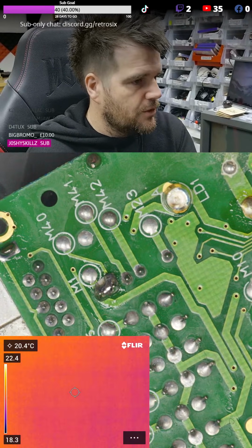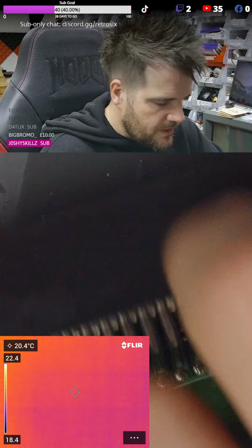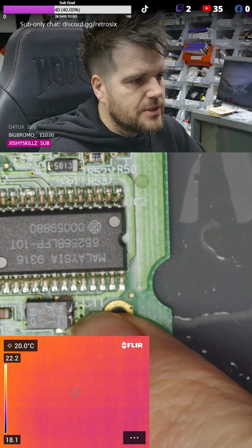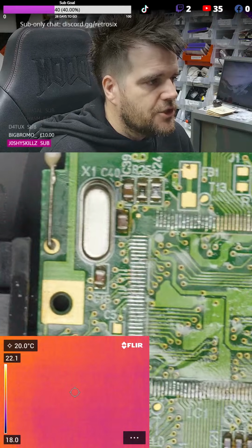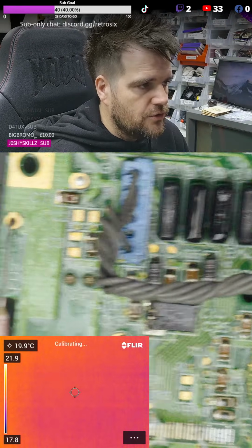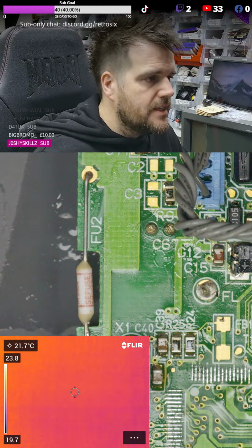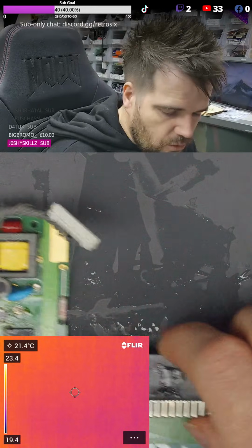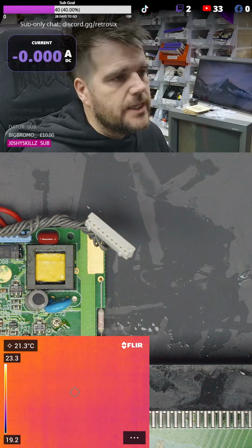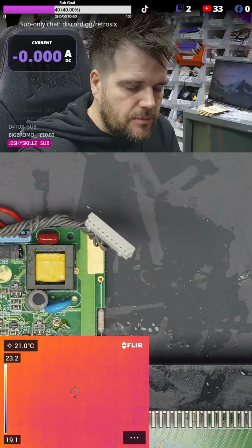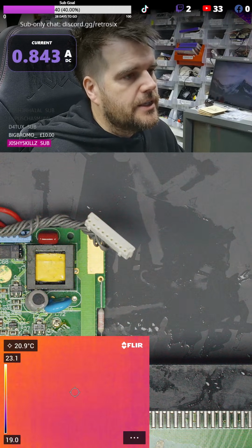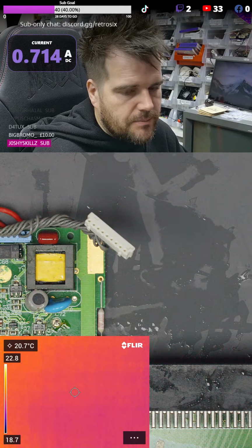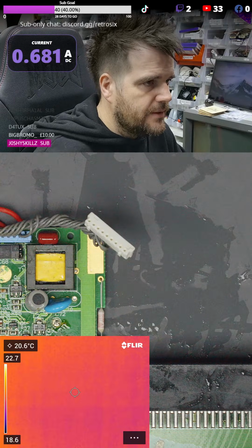This could also be if you've soldered chips down and accidentally bridged something. So say you were soldering this chip and you'd accidentally bridged 2 pins, you were swapping caps and you bridged 2 pins. A dead short is very easy to mistakenly do when you're soldering. The problem with this now is this is very difficult to detect, as you'll see. And there's a lot of ways that this can also throw you off, and I see it all the time. So now if we overlay the current, I connect the current back up to the bench, and you can see there, we now get 800 milliamps. We should really be getting 3 amps, but something else is limiting that current, and I know exactly what.